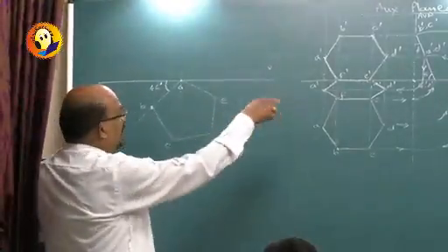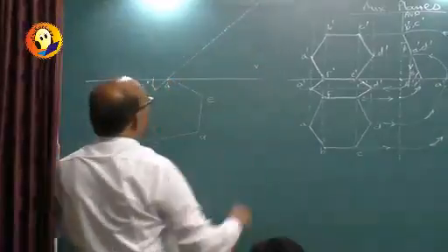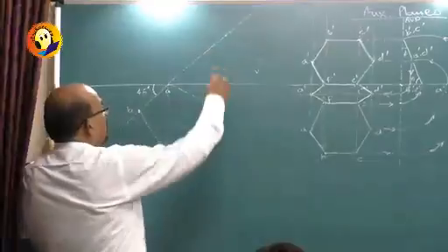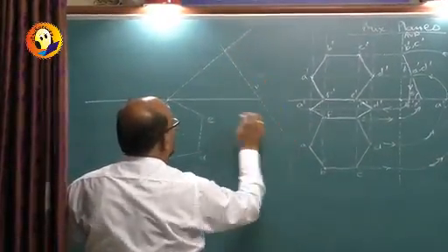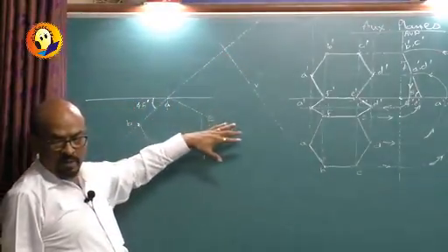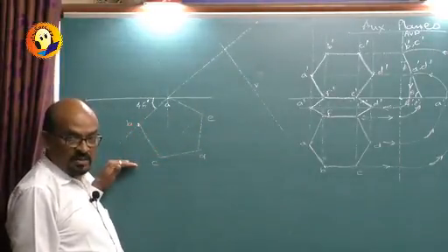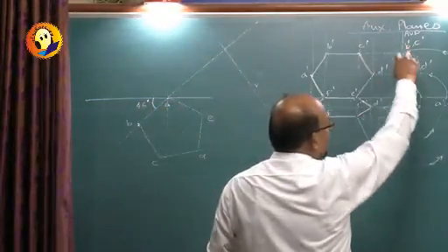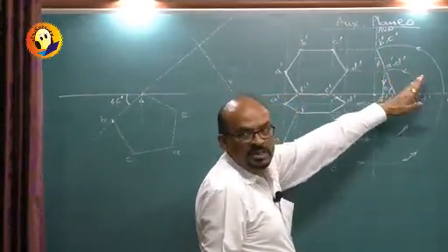So again, like in this case, we should take a plane perpendicular to it, because what is the policy? So I am taking a plane perpendicular to this AB, line of rotation. All other problems say that line of rotation should be perpendicular to XY. Our line of rotation is fixed. So we take XY perpendicular to it, is the concept. This was again another XY. I could have drawn the same thing over here also, but that is difficult. Side view is easy to imagine.